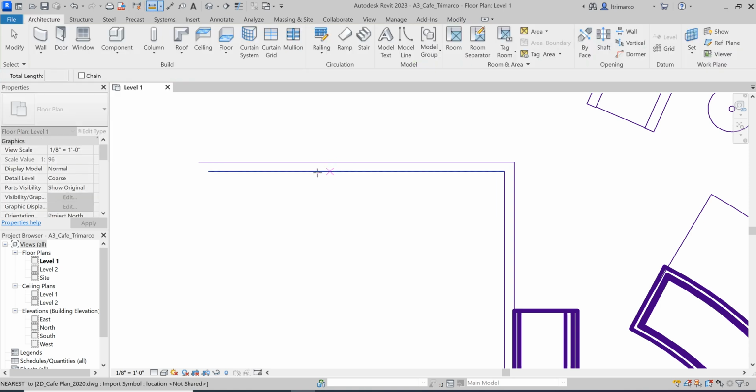I am going to select, notice intersection is popping up, but if you prefer to see an object snap like midpoint or endpoint, by all means, by moving along the line, or I should say the front face of one of the walls, is beneficial, all depending on how you like to work. Object snaps in Revit are automatically on. You can turn them off, but really they're super beneficial with building and understanding constraints in the program, so I highly recommend you keep them on. And mind you, how you change them is through the file pull-down menu called Options.